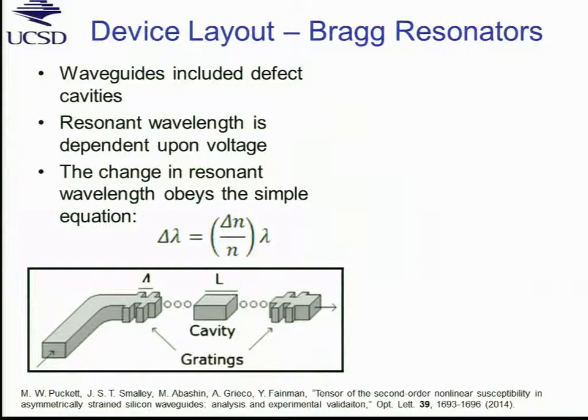For testing, we use, again, one of these Bragg resonant structures. Basically, you have a Bragg mirror and a cavity. And we observe the stop band and the transmission lines introduced by the defects into the stop band. And as we apply an electric field, hopefully the spectra in transmission will shift, and from the shift we can deduce the amount of delta N that we are getting.